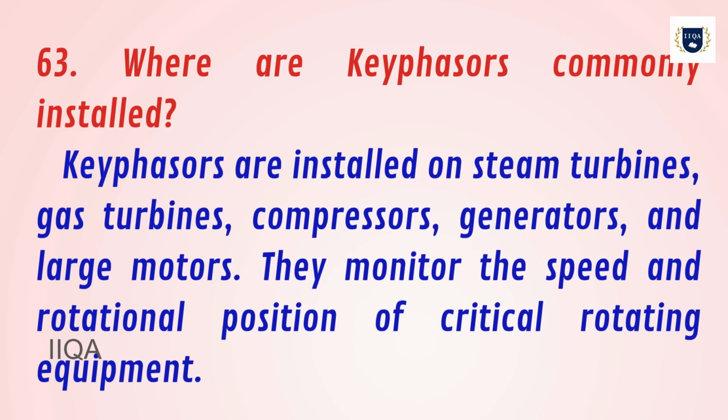63. Where are Keyphasors commonly installed? Keyphasors are installed on steam turbines, gas turbines, compressors, generators, and large motors. They monitor the speed and rotational position of critical rotating equipment.